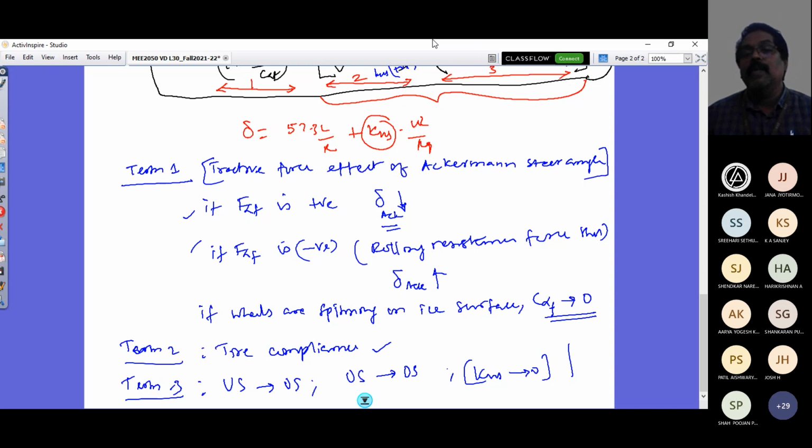So what is the condition? How can we limit that? All that we will have to study. And then the rollover stability problem. When you consider suspension, there is a lateral load transfer, but the lateral load transfer will not disturb the equilibrium of your vehicle. It will be disturbed the moment there is a limiting value of lateral acceleration. And if that happens, then the rollover cannot be prevented. So how can you quantify or understand that physics? That is what is left in the stability part.